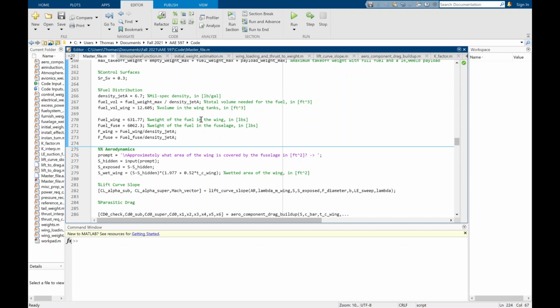The reason for that is that this is going to be a relaxed stability fighter that will use a 6 degree of freedom, or three-axis, flight control computer. So as long as you have adequate control surfaces and large enough tails, the controllability and the stability of the aircraft is less vital than, say, a transport aircraft that's held to different standards basically.